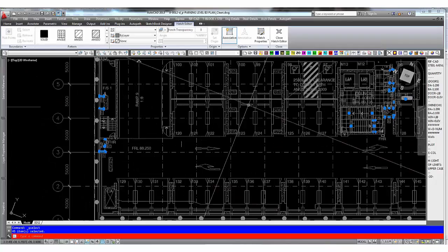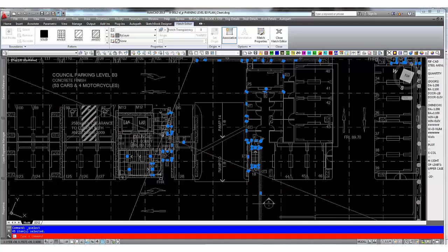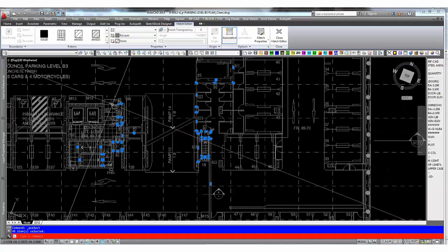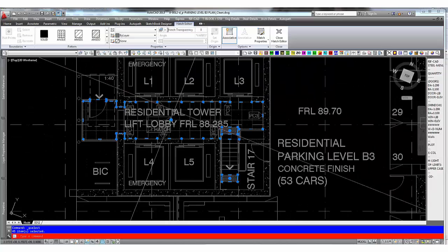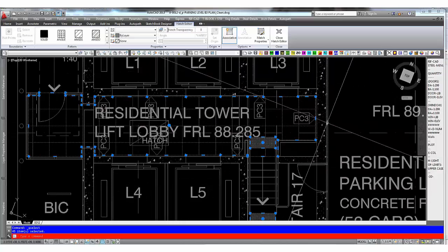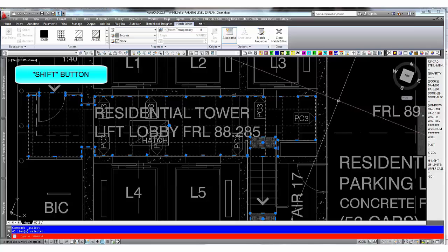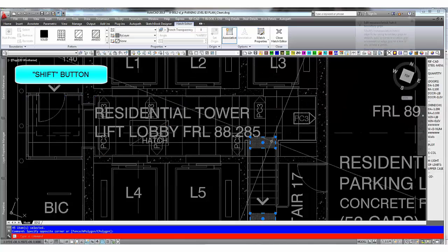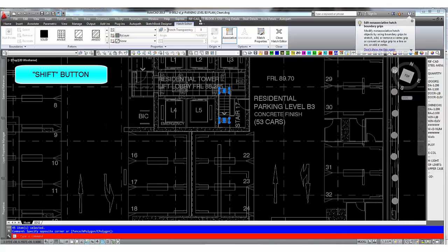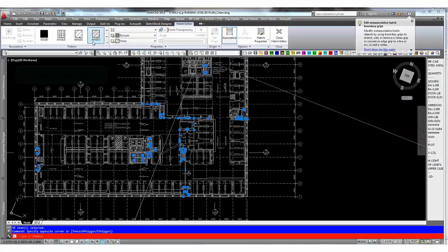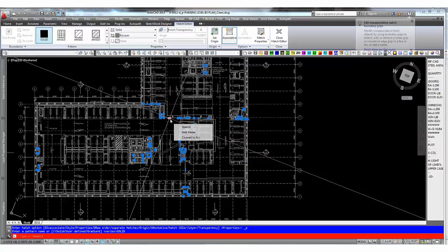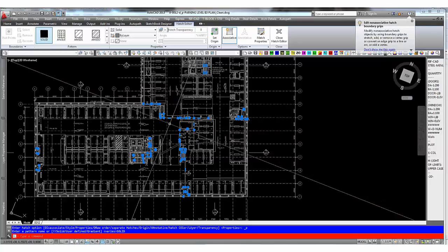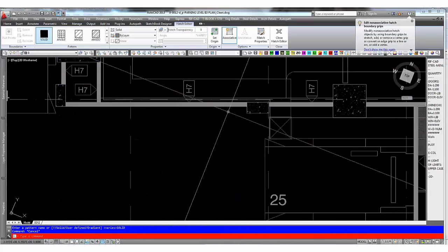You'll see that it's gone all the walls and so forth. But what it's also done is given these tiles. So I'm going to hit the shift button and deselect that. And now up here I can change it all to solid. You can see those walls have changed.